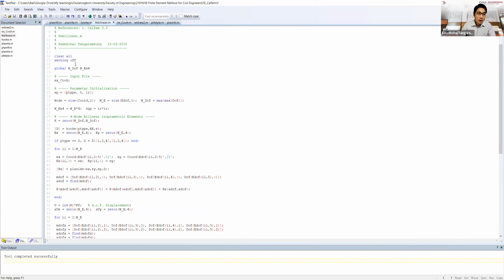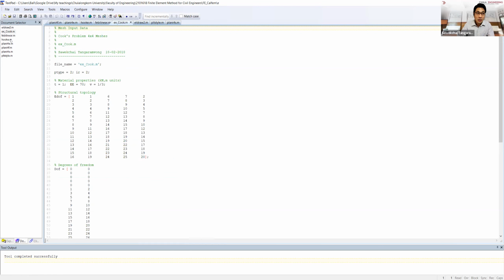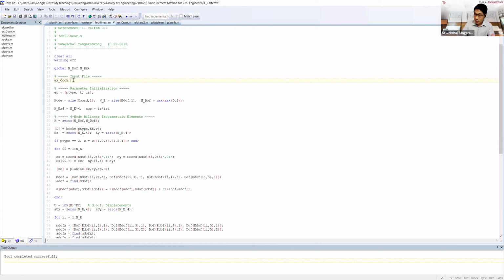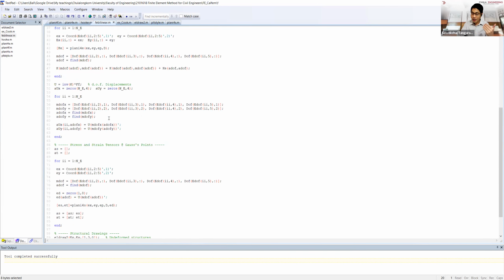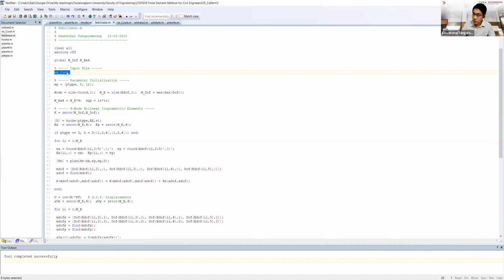And if you have a look here, I have put them in the different framework, starting from the input files, which is according to what the input you want to have. For the structures, you might name them, for example, structure A, structure B, structure C. Every time you change the structure, you just change these input files. The rest of them, you keep as is, and that will construct the matrix Ki, Bi, assemble the global K matrix, and assemble the force matrix for you, right? You just need to have this to be correct.